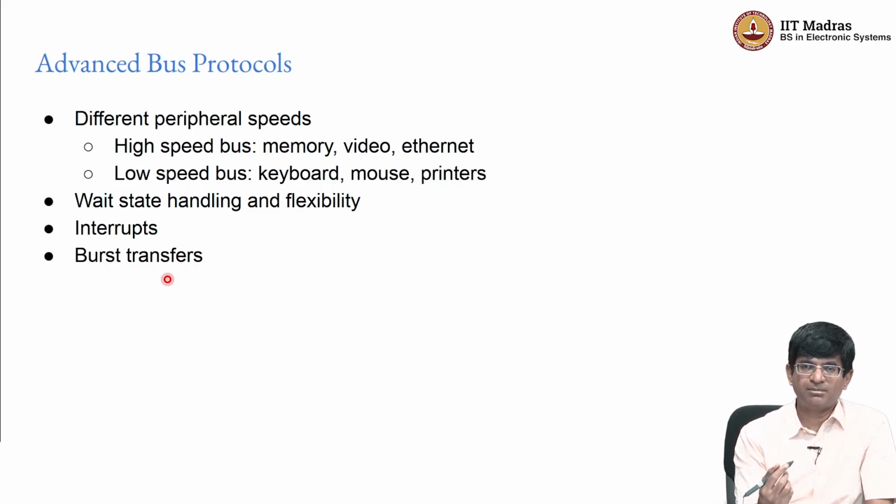The bus itself will take care of generating the successive read and write addresses on its own without any other logic intervening. They do this because this is a fairly common kind of operation. There are many scenarios where you want to copy chunks of data from one set of addresses to another set of addresses. So why not make some extra hardware support for it?